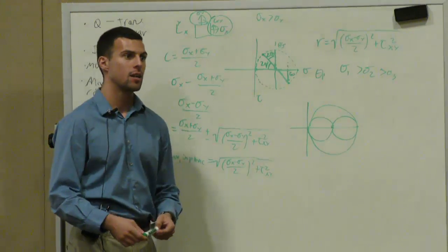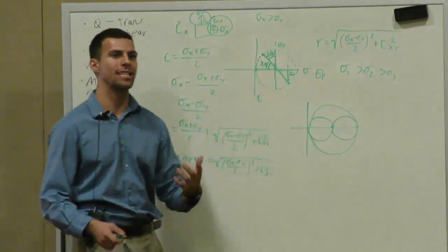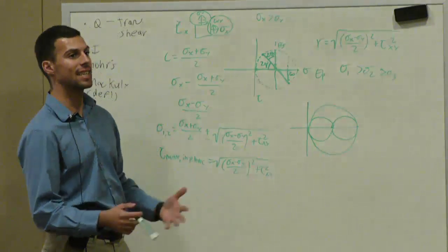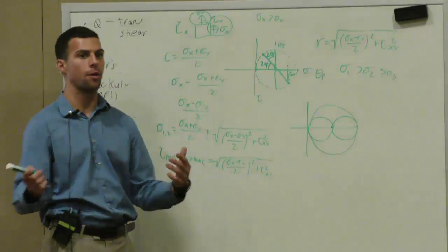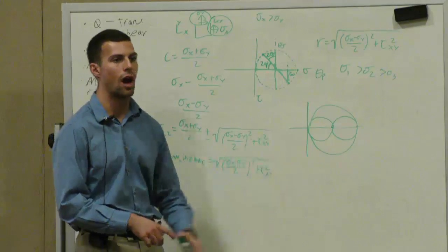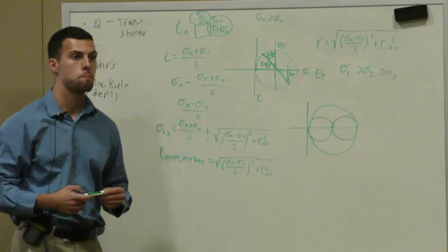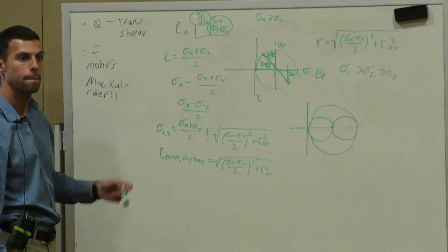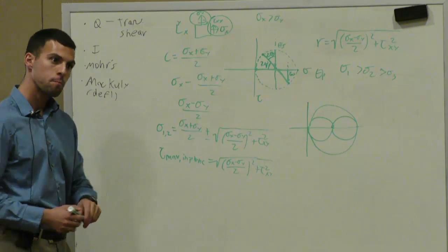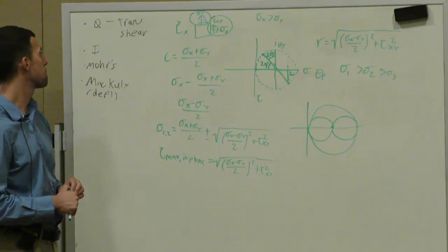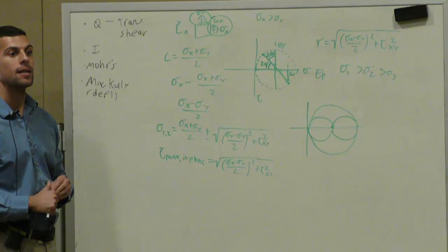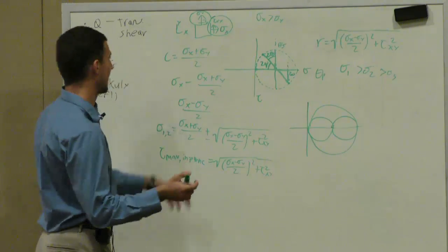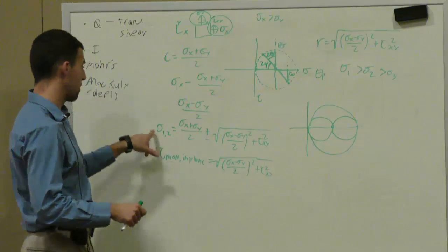All right? So do we understand now what Mohr circle is and why it's established? As I said before, it doesn't give you any extra information over the pure equations, but it's a nice graphical representation. Yes? And so that's why sometimes you'll have a Mohr circle that has the origin point in it, based off of whether or not the sigma y and sigma x are positive or negative. That will determine where your Mohr circle is located. Exactly, this can determine it, or this can determine it.